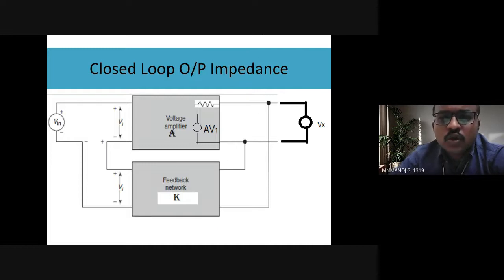Next one is the output impedance. Okay, now output impedance, the resistance would be in series. This is the voltage gain. Now there are some rules which you should keep in your mind when you are doing the output impedance calculation. One is you need to nullify the input. Okay, input has to be made 0 or grounded. So this part of the circuit gets completely negated.